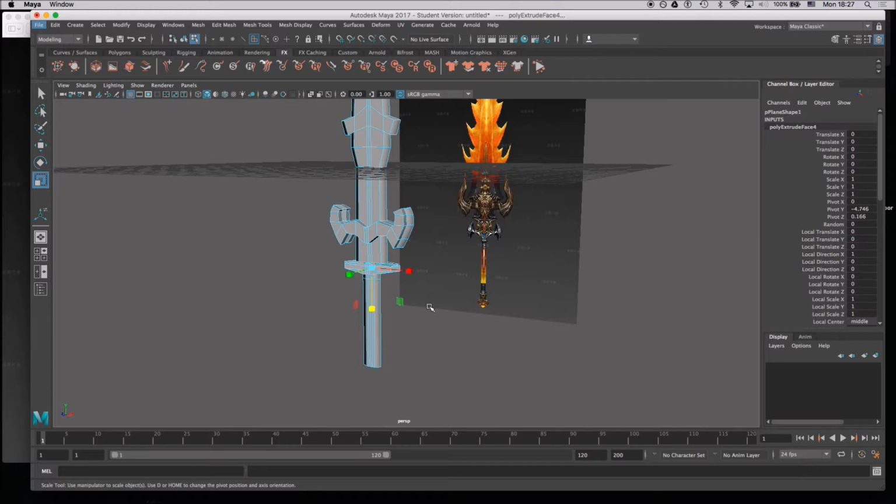Yeah, so the problem is that now that you can use the edges, now we have a quad here. Now this is a 1, 2, 3, 4. And so now that it's not a line, that's one of the reasons why. So what you can do is you can actually go and delete the vertices that are causing the issue, and as long as you turn that back into a quad, then you should be able to add your groups back.